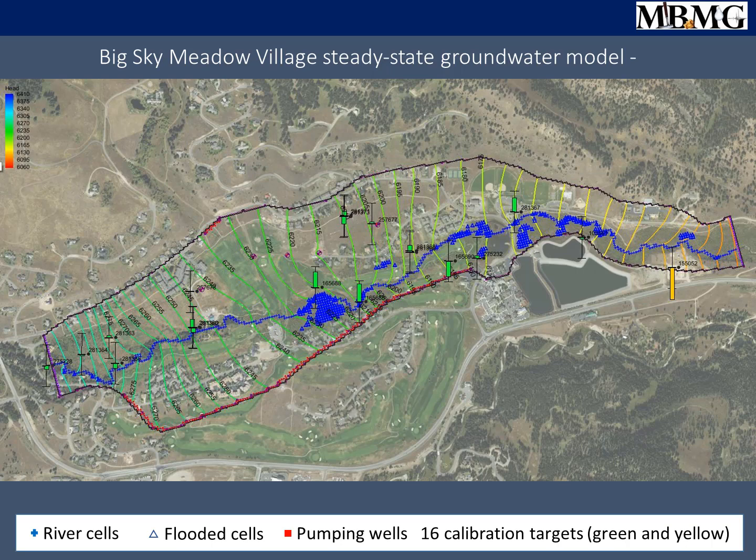So I thought, well, let's just take a representative. We'll start with 100 feet per day, a mid-range value, and then use the storage coefficient from the 2 wells that had observation wells. And interestingly, the storage coefficient was 0.032. And for unconfined aquifers, we often think in a range of like 0.15 to 0.01, you know, how much water you can hold in the sediment. So it's a little low, but it's still within the normal range for an unconfined aquifer. And using those values, it actually calibrated pretty well. But then it wasn't perfect. There were a few more yellow bars. Here's one way over here at the edge of the model.